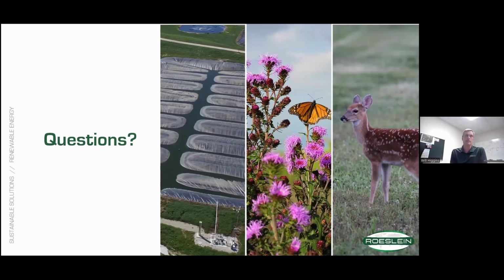Now, when we talk about lagoons, they're not small, right? These are lagoons that are probably containing anywhere from 15 million gallons to, we've got some as big as like 40 million gallons. And so you can imagine heating that many gallons of liquid, and then it's losing energy to the earth, right? Through just natural convection to the soil, because the soil's at 45 degrees. And then it's losing some off the cover because of wind, convection heat, but it's gaining some from the solar. But at night, it's not gaining anything.